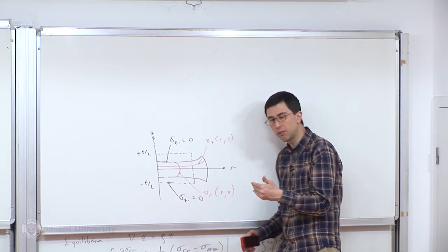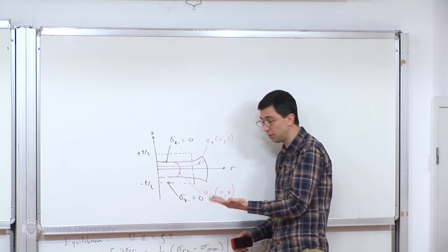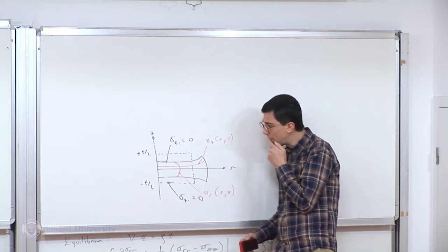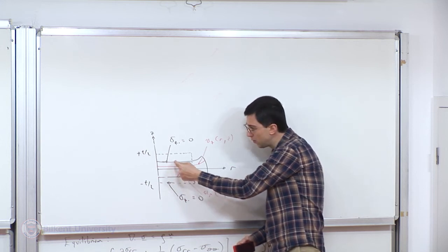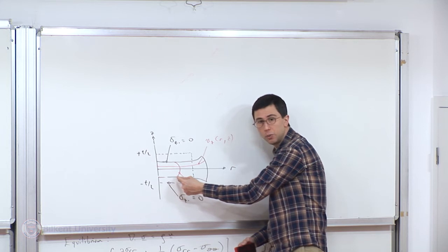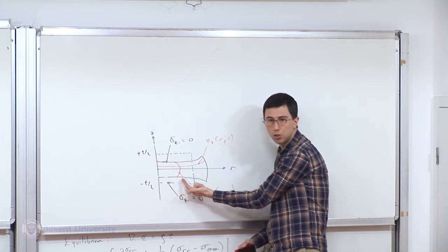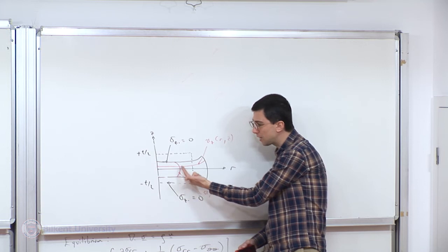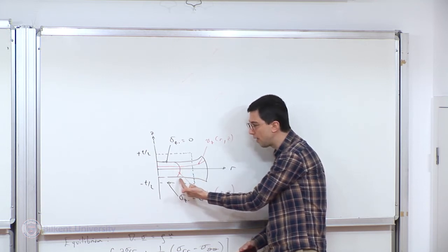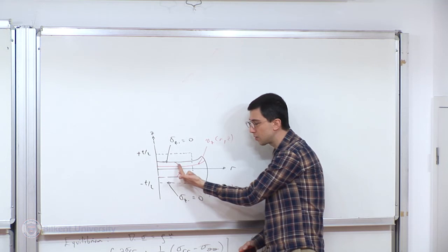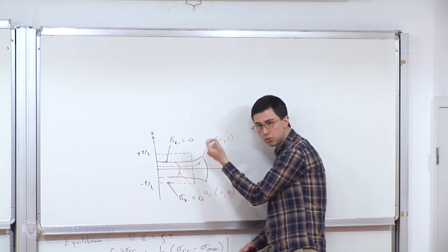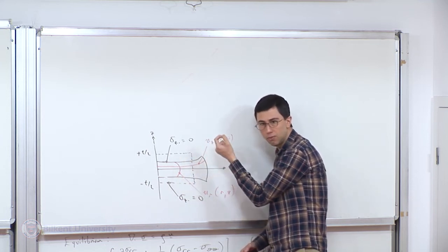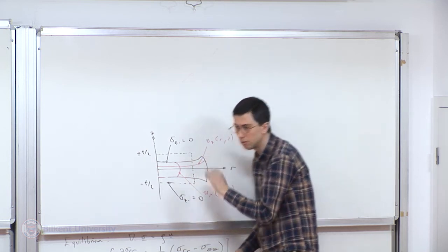So the dependence, and therefore UR comma Z, remains appreciable in certain regions, but the change is small. It is there, but it's small, okay? So the arc of UR variation with Z is not as prominent as is shown here. It's there. So to eliminate that slight dependence, I'm going to average or integrate over the thickness direction and divide by the thickness. That is called thickness averaging. So to eliminate this small but certainly present dependence of that variable on the Z component, okay?